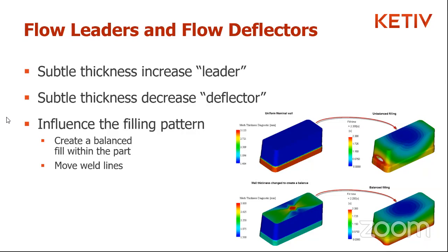And so bringing that to the part design is a huge advantage. These integral gating built into the part design, or flow leaders, flow inhibitors. When you take a look, like I do, tear things apart and you see a plastic component that has these things built into it, you know that that's a good designer who thought that through. Yep.